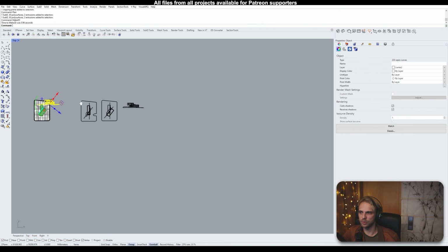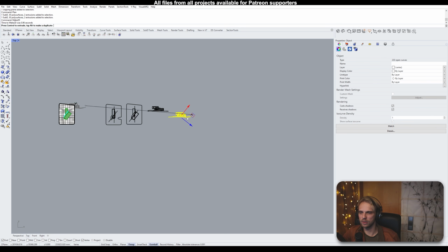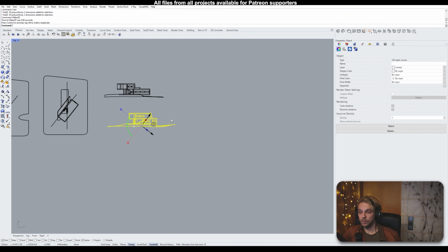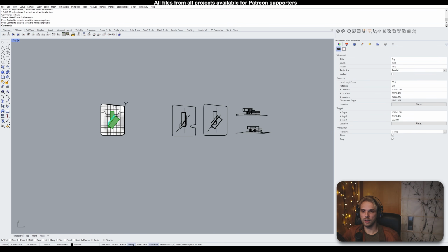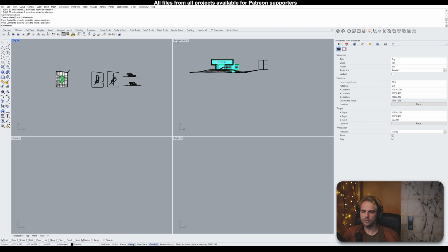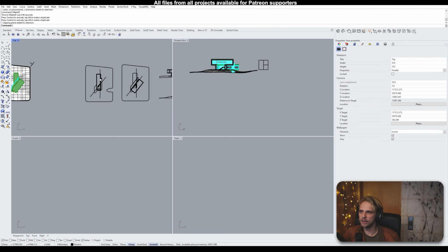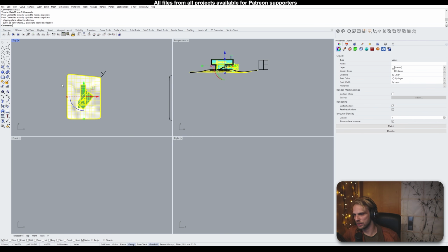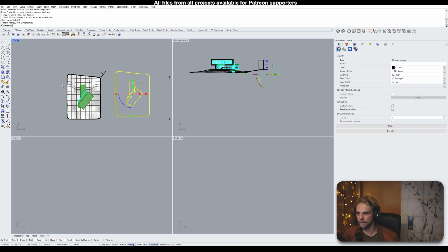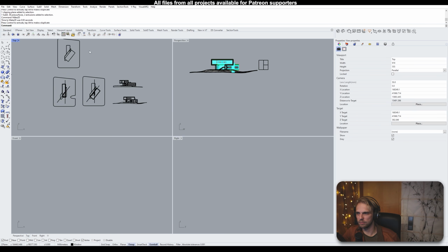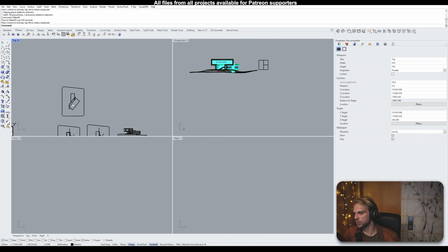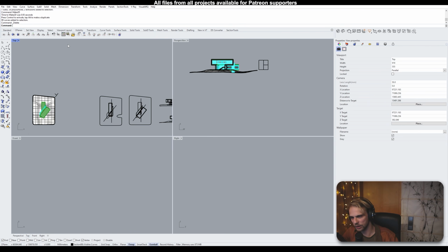There we go. Let's go back to the top view. We have our section BB, and that is going to be that. A facade is literally just a section that is not cutting through the building, right? So if you know how to do sections, you know how to do a facade. A site plan is just a top view, like it's just this, make 2D. That's the site plan. It's basically a plan with no clipping plane, right? So we're not going to be dealing with the site plan.